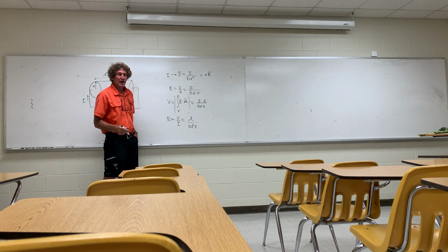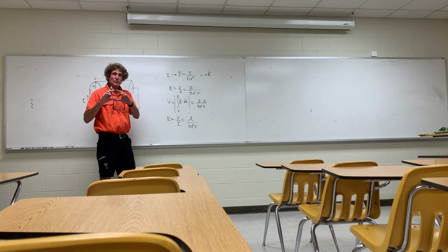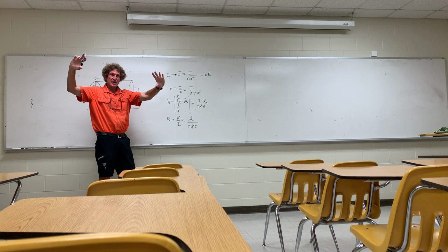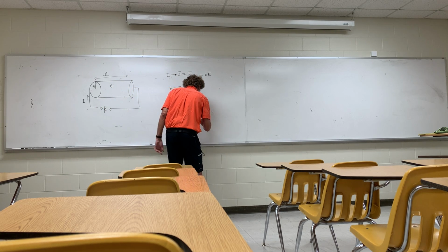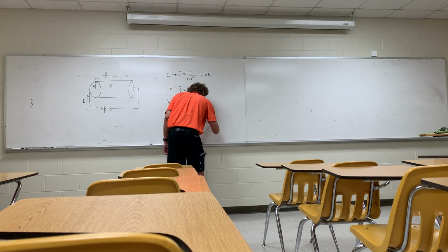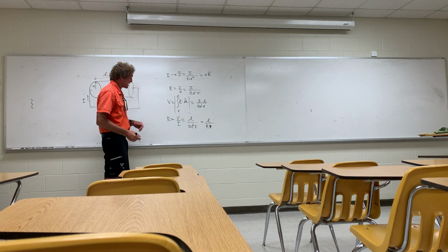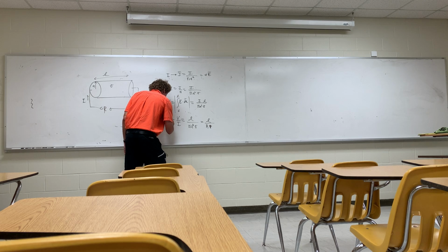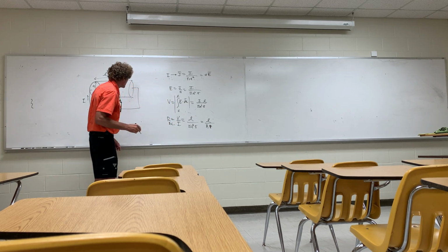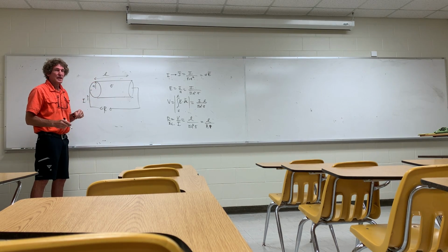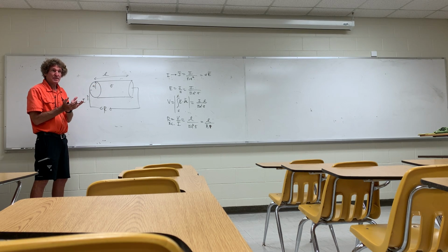Now the real thing, and I try to really make sure you understand, regardless of the cross-sectional shape of the wire, if it is a constant cross-section, and it doesn't blow up like an actual conic section or something, then what you really have here is resistance proportional to length, inversely proportional to cross-sectional area, and inversely proportional to sigma. That's the general form of resistance. But that would be the DC resistance, because we've assumed that the current had no time variation and was uniformly distributed.